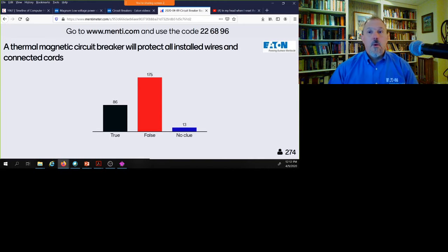Now, what we learned over time, and what we had a class on last week, is the arc fault circuit interrupter that basically looks for damage in those conductors, arcing and sparking that can cause fires. That technology basically lowers some thresholds. We're looking at signatures and can provide protection for those conductors, those connected cords. But in reality, those breakers are protecting the conductors that are behind the walls, the conductors that are connected to it. That's what it's there to protect, not those cords that we plug into the wall.